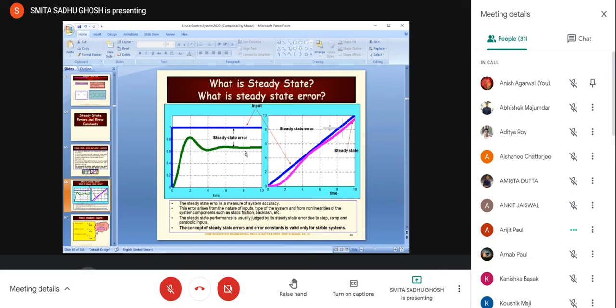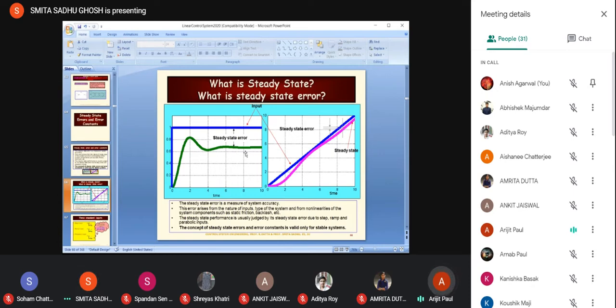It's a linear system, a static system. But an RL circuit in case of DC, can we say it is nonlinear? It will be saturated. RL, no. If it's RL, the response is going to be somewhat similar to whatever you see over here on my plot, the green response, not the same, of course, but somewhat. It's going to have some transients and then go to the steady state value. It's not going to be nonlinear.